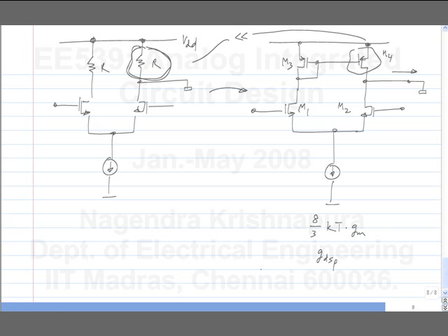Or 4 kT times the conductance. And what is the output conductance? That also G. Okay. Now we put this transistor M4 so that we get a much higher output resistance or much lower output conductance. Okay. But that same doesn't hold for noise. It gives you a much lower output conductance, but noise is in fact more than this one.